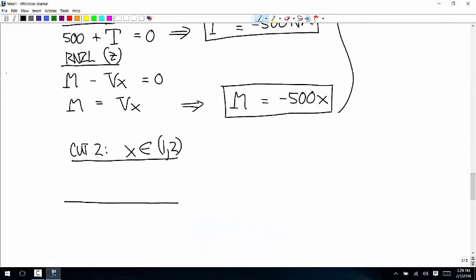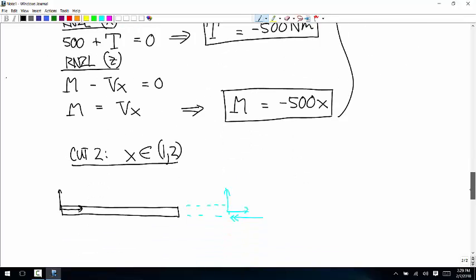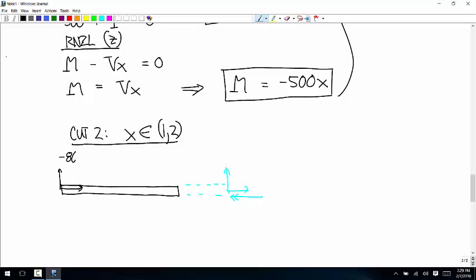All right, so here's the piece we're isolating. Here's the piece we're ignoring, and that still has a force vector and a couple. So those are not going to appear in our calculations. We have the force vector of negative 866, negative 500.